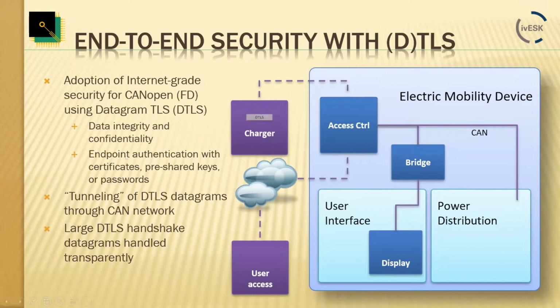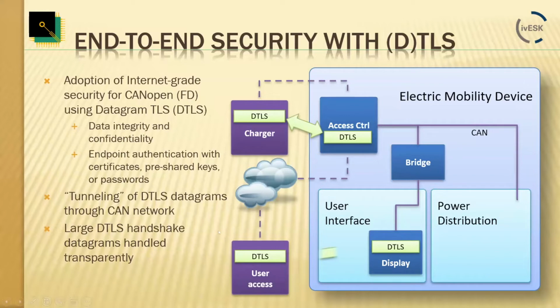So the best use case for the DTLS is really not as much the communication directly within a system. That would, of course, also be possible. However, we see the real advantage here for anything leaving the system. So whenever we have some communication that leaves the CAN system and want to reach the outside world, then DTLS is by far our best option to ensure that we have authentication and potentially also encryption and proper security handling going in and out of the system.